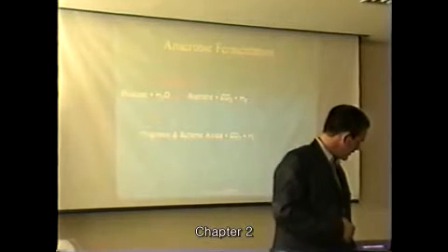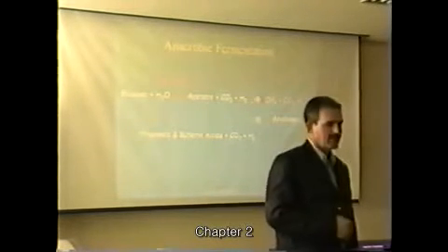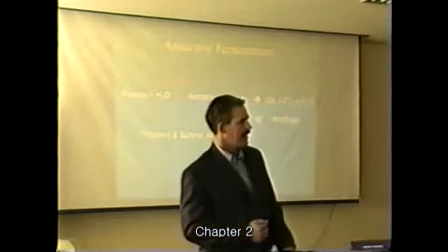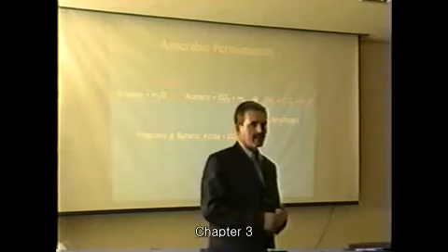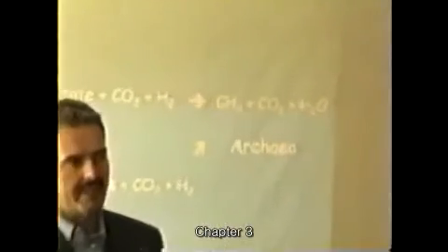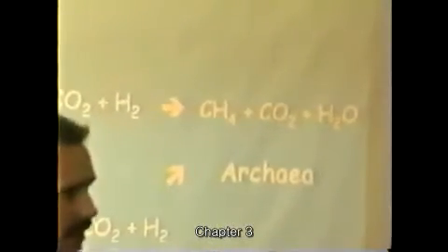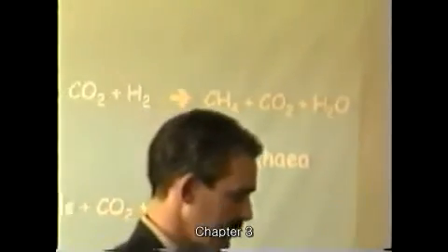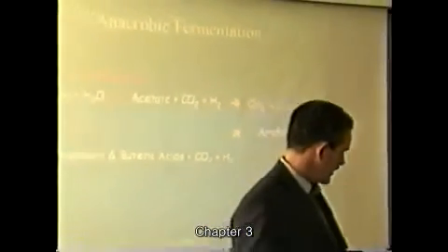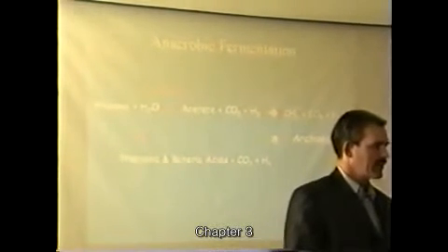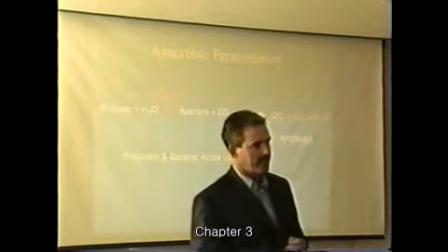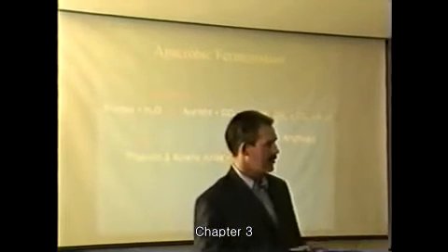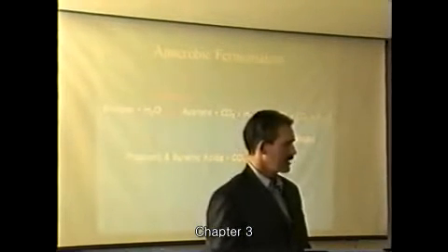And the guys that do that work are archaea. The methanogens have always been classified as being bacteria. They are not bacteria. They are archaea. They've been reclassified. The interesting thing is, if you're looking at an anaerobic digester, the population of archaea in the digester is only 4% of the total. The rest of it is all bacteria.